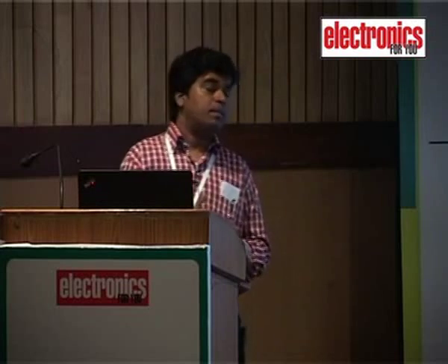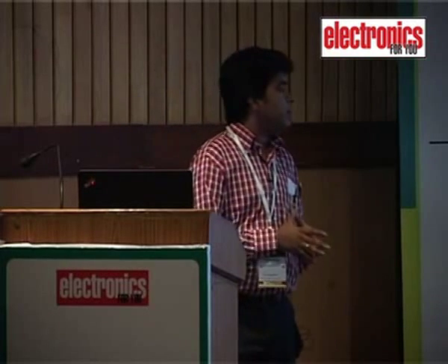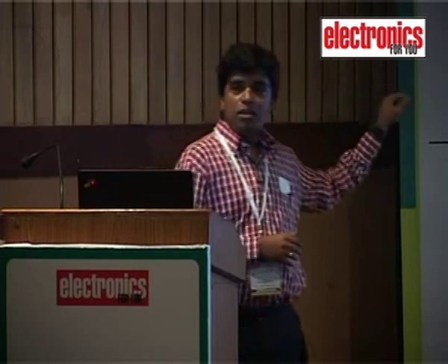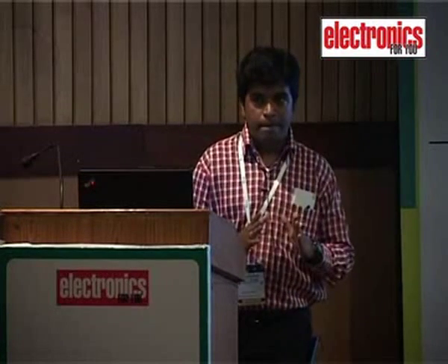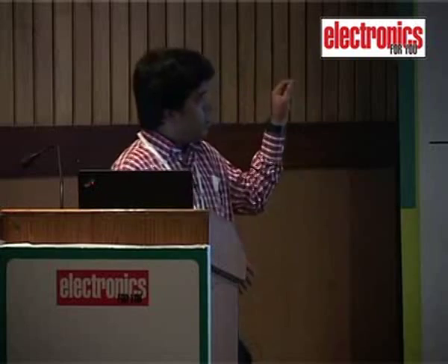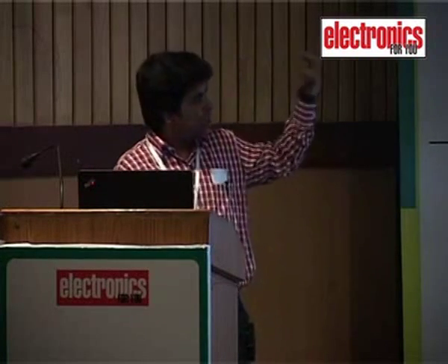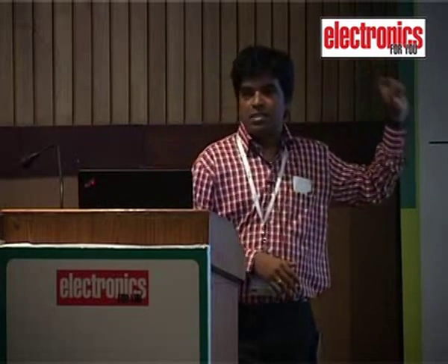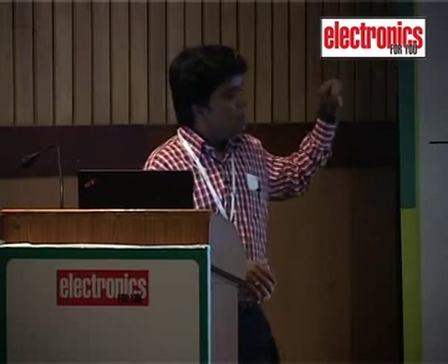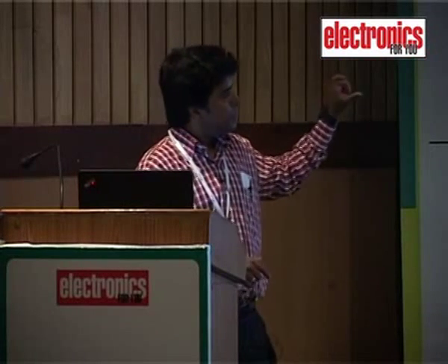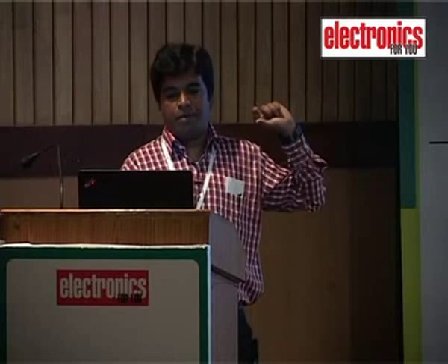This is how red, green and blue from their 24-bit representation are compressed. The plus sign we see here can be considered a logical OR. So red bits 7 and 6 are ORed in order to get a single color pixel bit for C7. The 3 bits of the color pixel we get at output represent only the red component.